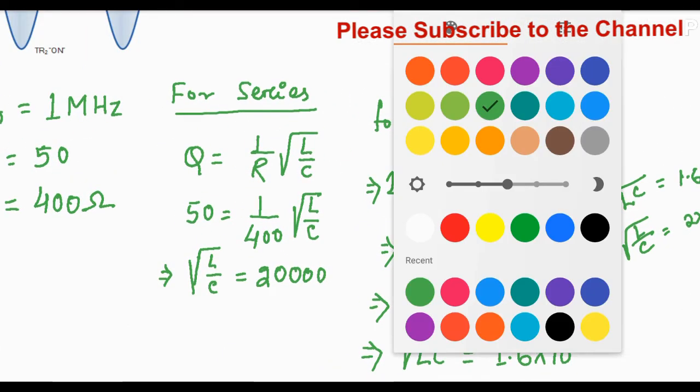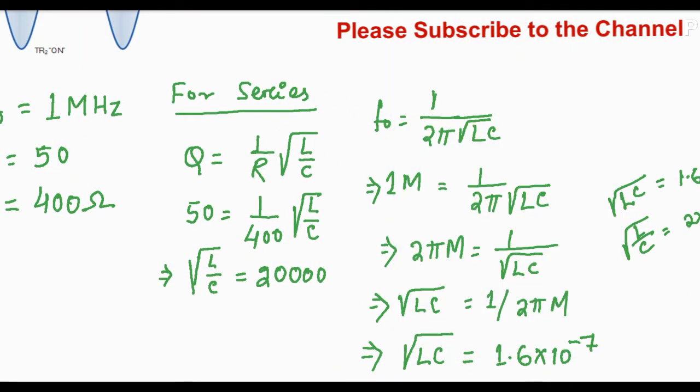In case of series, the quality factor is given as Q is equal to 1 by R root over of L by C, and quality factor is given to be 50. So 50 will be equal to 1 by 400 into root over of L by C. So we are getting that root over of L by C is equal to 20,000, and we can apply another formula, that is F0, the resonant frequency. Resonant frequency is equal to 1 by 2 pi root over of LC.